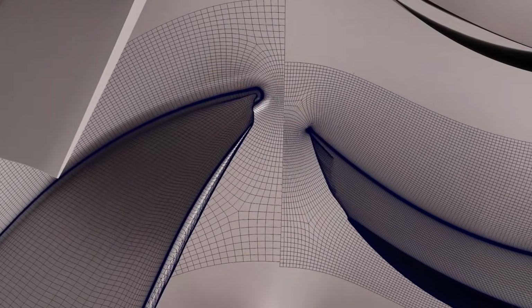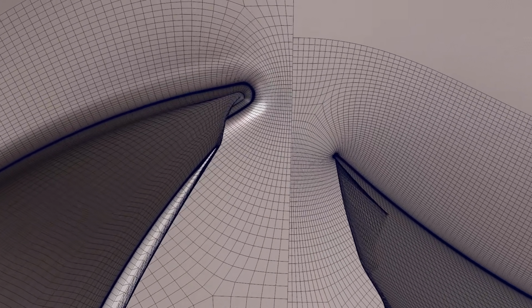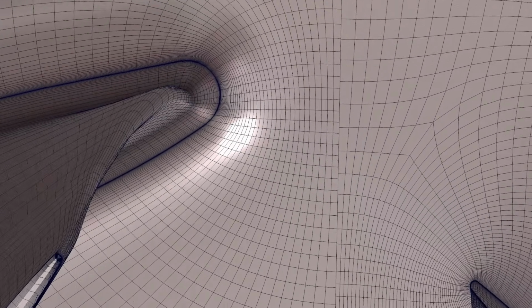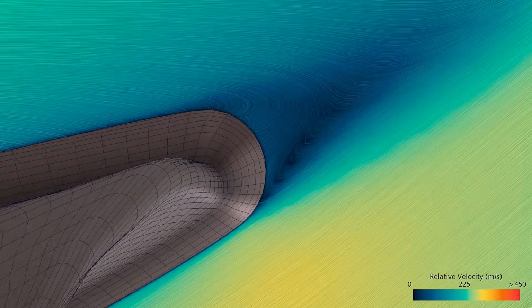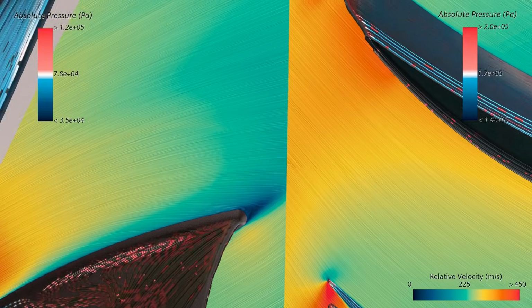So you said at the beginning you are product manager for SPH and turbomachinery, and now you already spoke about SPH, and now back to turbomachinery, I would say. Yes, exactly. So in Simcenter STAR-CCM+ 24.2, we are also releasing a turbomachinery feature. Now in the turbomachinery structured mesh, we now support the fillets for the blade. So the fillet can be either at the hub or at the shroud. And to be able to use it, it's really seamless for the user, because you just need to have your fillet surfaces with the blade surface, and there is no additional user input.